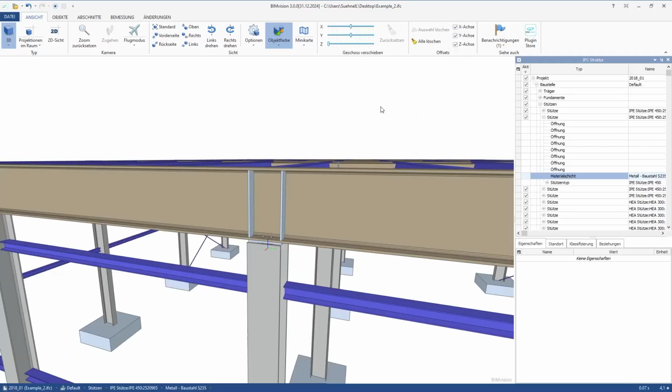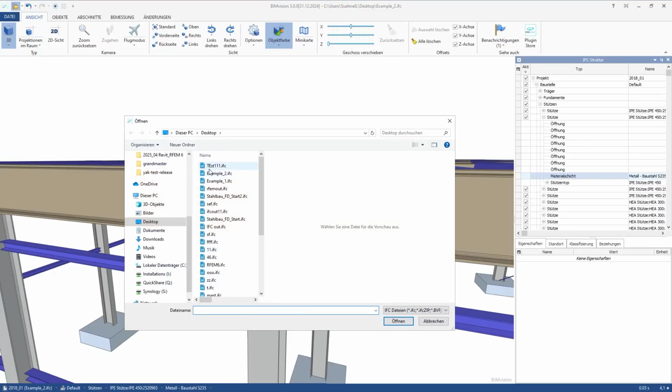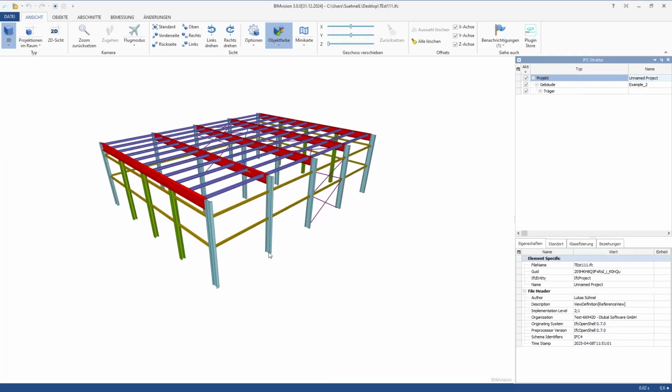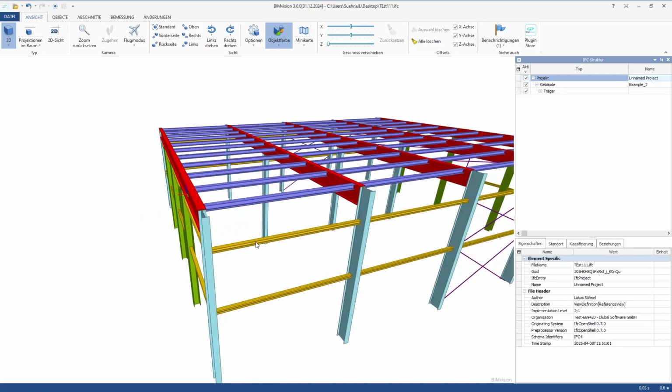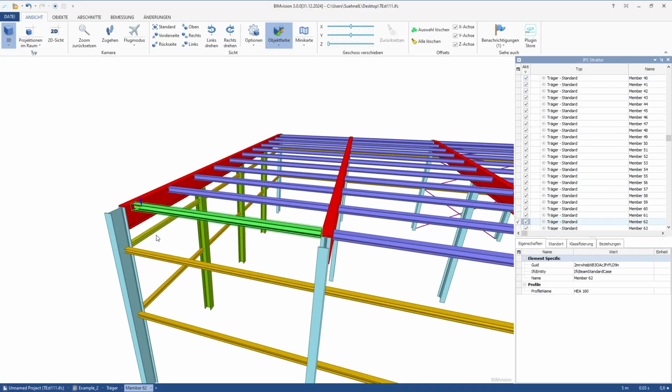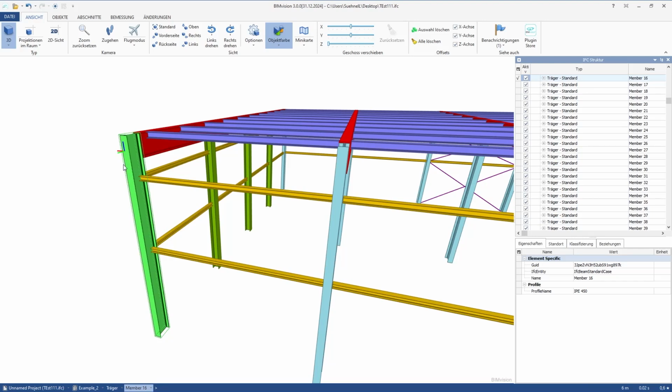Let me show it. Here with the colors according to the section rendering. And the good part is, because we save the information from the IFC file in our objects, we can also use it in our export again. So the exported IFC members have now the same GeoID that they had when we imported them from the IFC file.